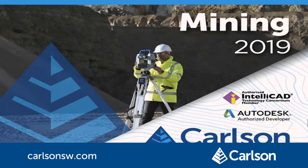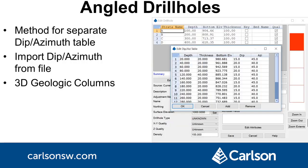Now let's look at Carlson mining. Support for angled drill holes has been expanded. You can now have a table of dip and azimuth values by depth that is independent of the strata list. The dip and azimuth data can be imported from a separate input file. Draw 3D geologic columns has new options for labeling along the angled drill holes.